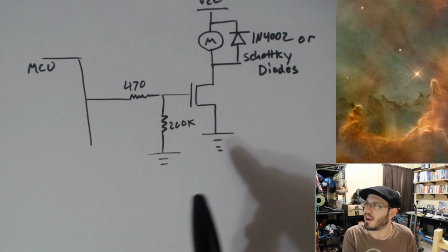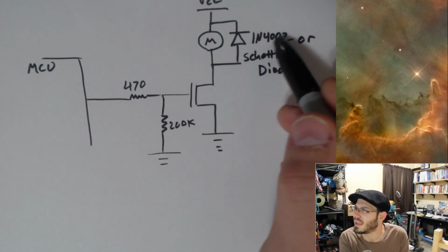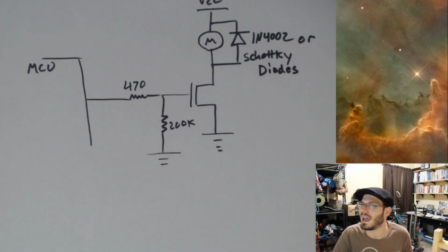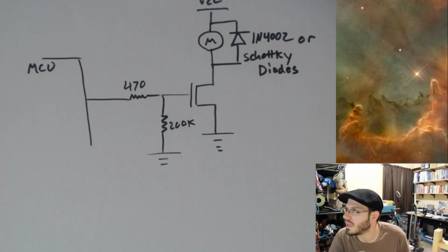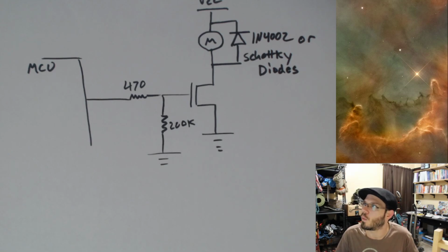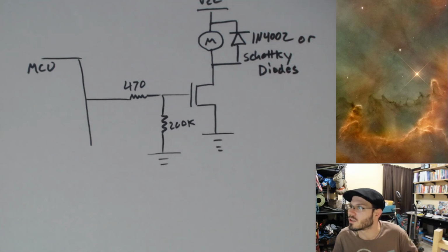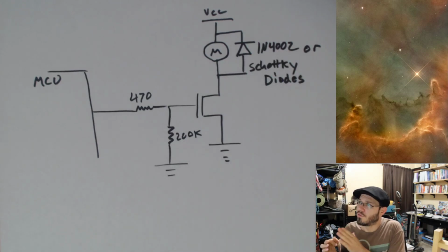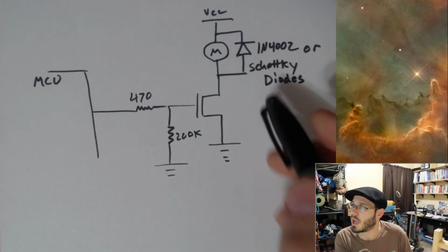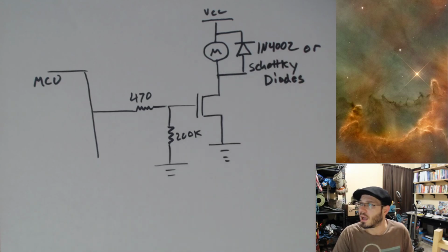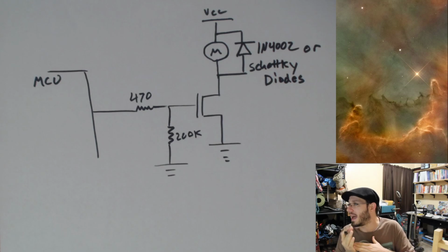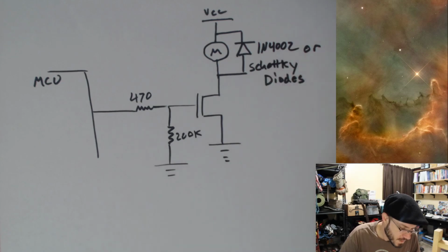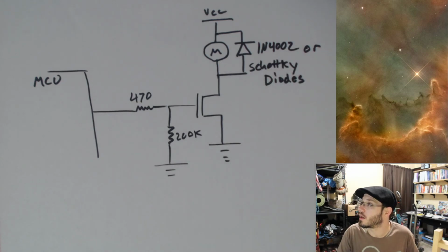Schottky diodes can switch very fast. We're talking maybe an order or two of magnitude better. So a Schottky diode generally can switch in 30, 40, 60 picoseconds, where a 1N4002 is going to be a bit slower than that. And switching quickly, changing from conduction to not conduction, is what I'm talking about when I say a diode switches. Going from reverse bias to forward bias, that switching action, Schottky diodes can do it much quicker.